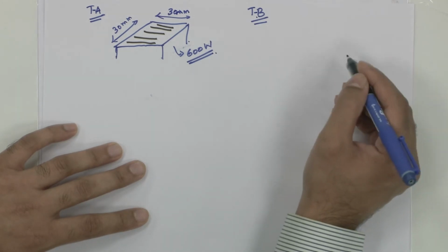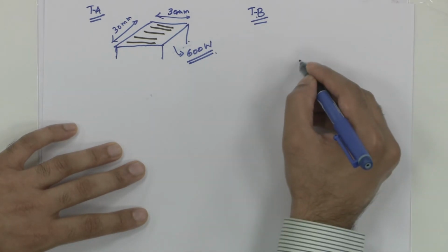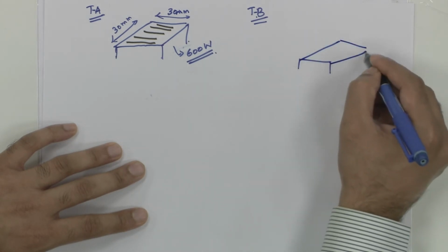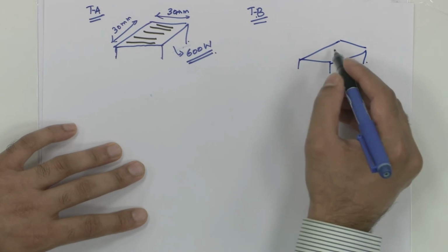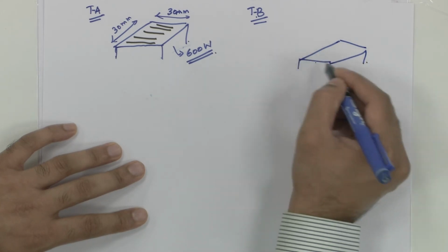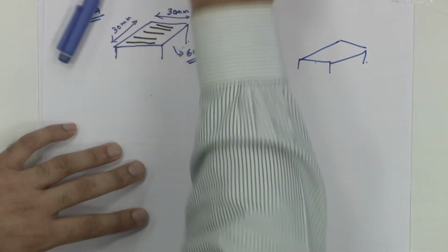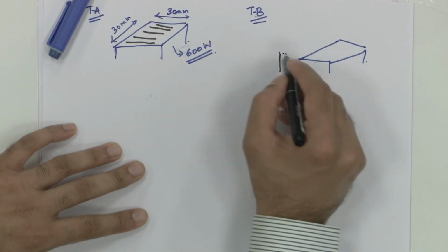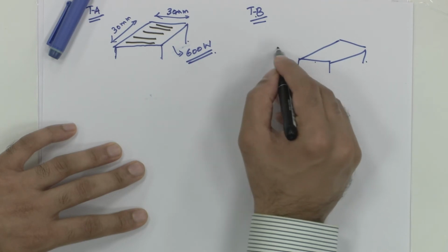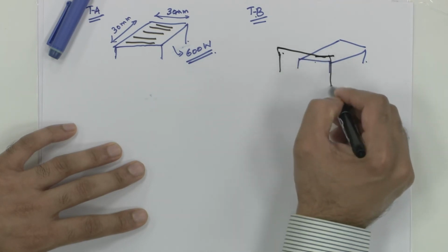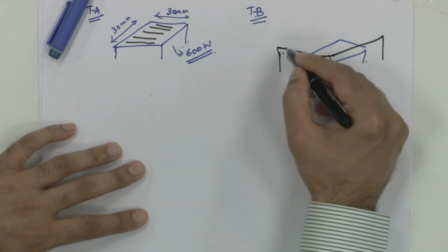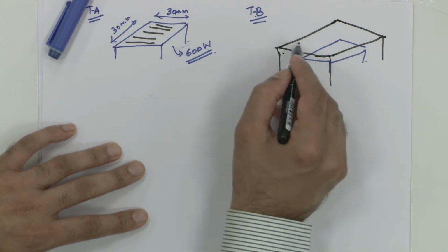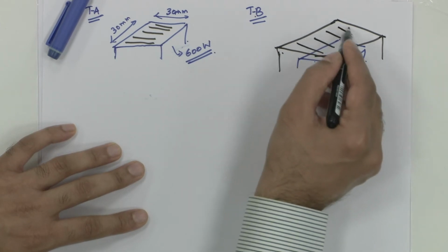So, what they are suggesting is that they take a heat spreader, the same silicon device that is dissipating 600 watts, but instead now it is spread on a much larger area, and then they put down their microchannels on this.